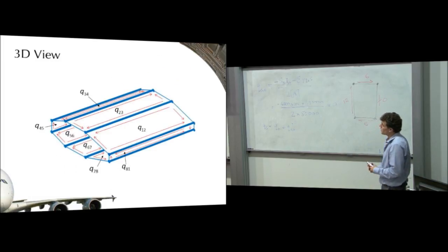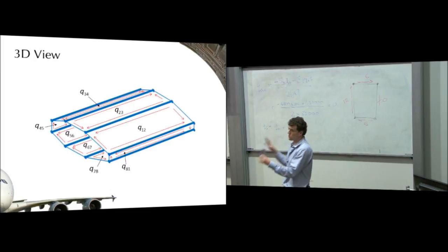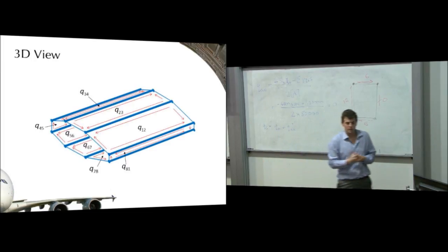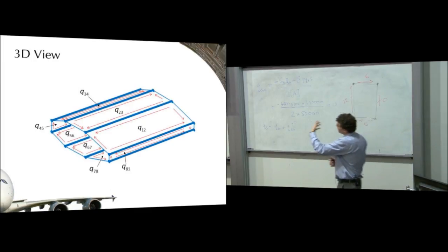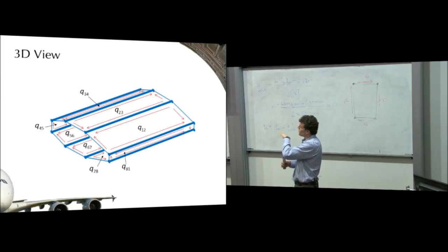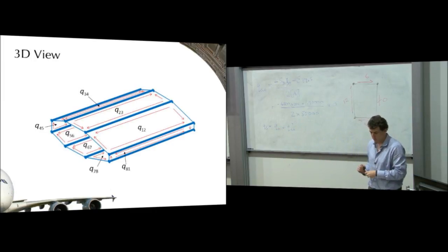And always keep in the back of your mind the three-dimensional representation of what we're doing. We've idealized our structure from being skins and stiffeners to booms and panels. And in those panels, the shear flow is constant. So in 3 dimensions, anywhere in the panel, if we test the shear flow, it'll be the same value. Okay, so if you need to do equilibrium in the 3rd dimension, that's fairly easy to do.